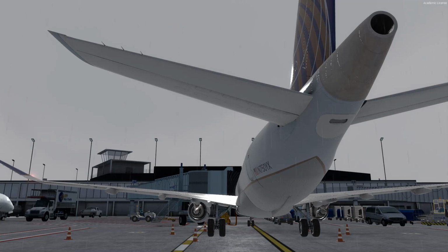Not maybe, we will take a hit. Maybe we can't comply with it anymore. So we'll need to lower our maximum takeoff weight even more to make sure that we are out-climbing whatever requirement it is. So we need to make sure we're capable and legal to perform the departure procedure. Later on in the climb, using the anti-ice would cause a lower climb angle, which would make it harder to out-climb certain threats. It could be altitude restrictions, ATC requests, traffic, or even weather.